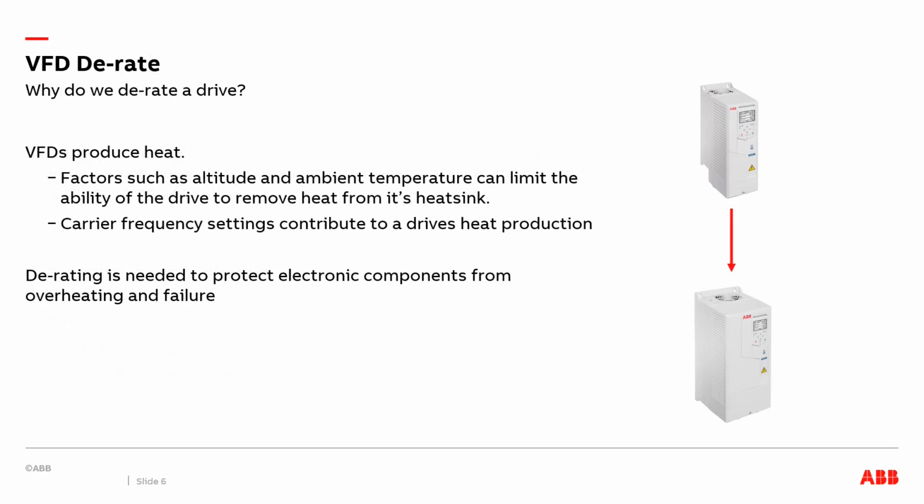So why do we want to derate a drive? Well, VFDs produce heat. The things that produce heat on the drive are the input diodes and the IGBTs or transistors on the output. If you look at how a drive is actually built up, you'll see that almost half the weight, if not more, is the aluminum heatsink on the back. And that aluminum heatsink helps dissipate all the heat that's generated from those input diodes and output IGBTs.